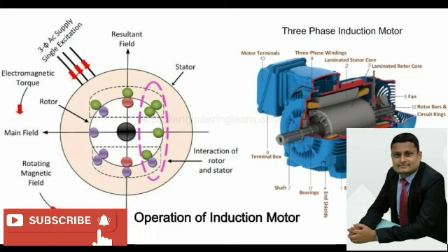Stator winding: double layer lap type winding with diamond shaped coils is used for large motors, with 2 conductors per slot. For medium and small motors, single layer mush type winding is used. Each coil occupies 2 slots.